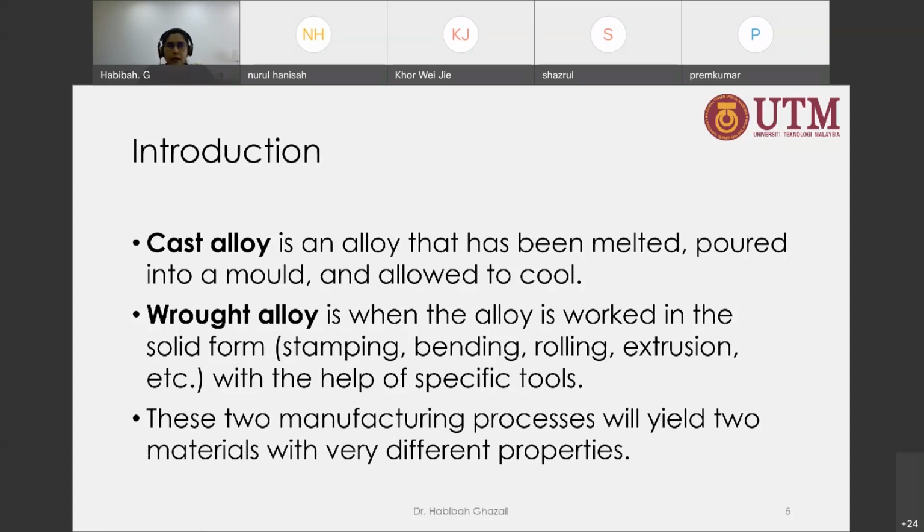So we can have an aluminum alloy that has, for example, copper as an alloying element, but one composition has a small amount of copper and the other has a large amount of copper. We need to process them differently into their final shape, because the one with the larger amount of copper will become brittle compared to the one with the smaller amount of alloying element.